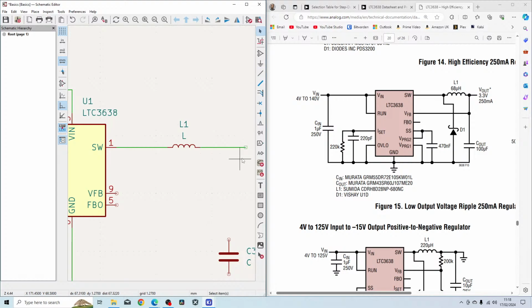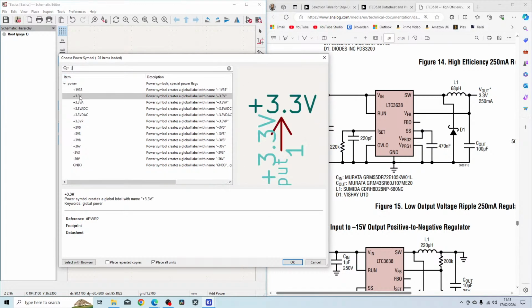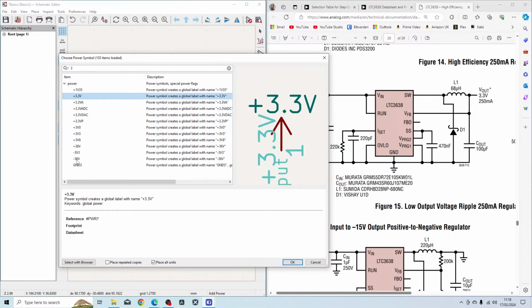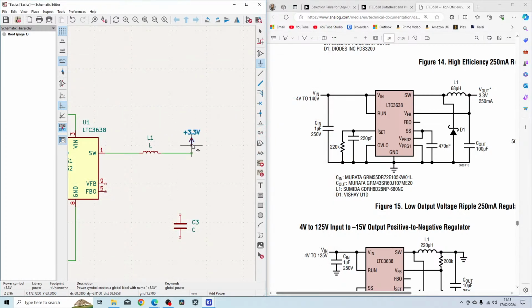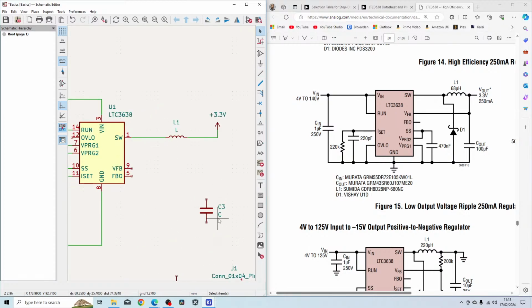And then this goes out to the 3V3. I'm going to put down a power plane. This is where I like Altium a little bit better. I like the power ports with the bar on top. I don't quite like these arrows. It's just maybe weird, but whatever. That'll be fine. So we have our 4.7, and we have a connection to the VFB pin, and we have a DRC, so a no connection flag, on this pin.